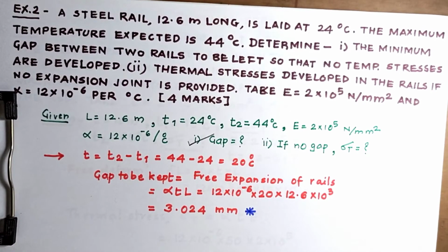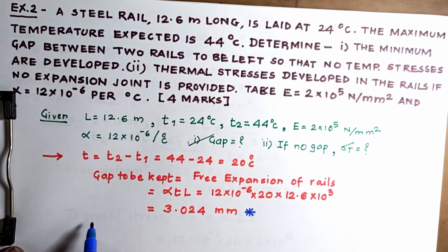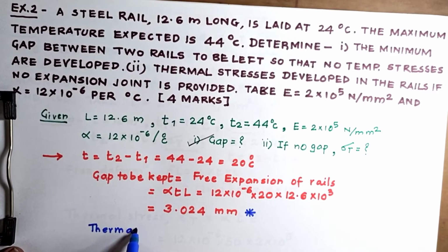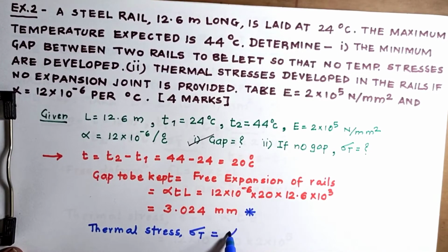Now we have to go for second. If no gap is kept, what will be the thermal stress induced? We know that thermal stress, how do we denote thermal stress? Thermal stress is denoted by sigma T is equal to alpha into T into E. Put down the values.